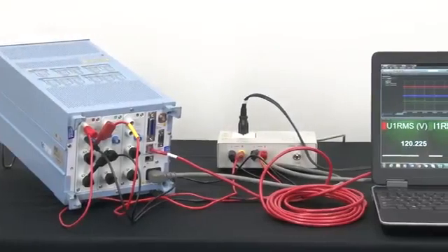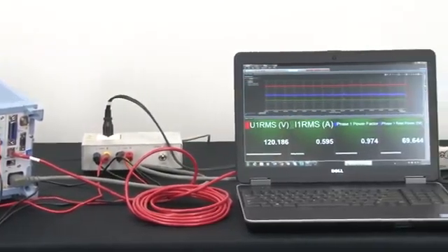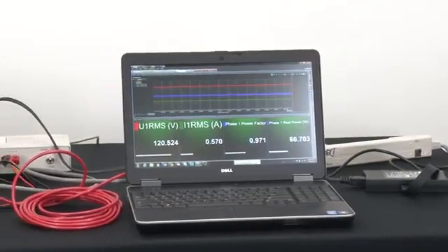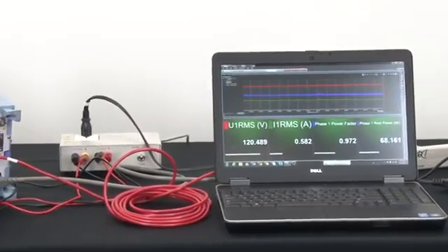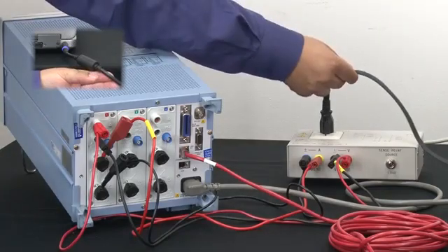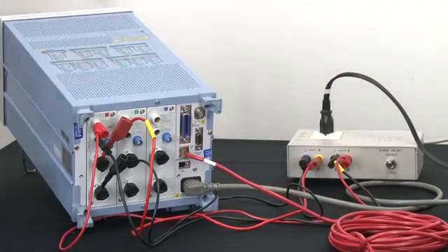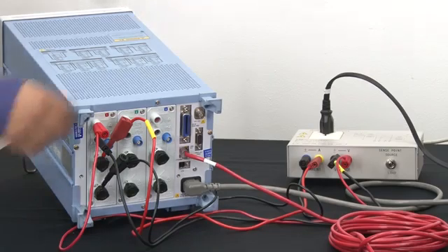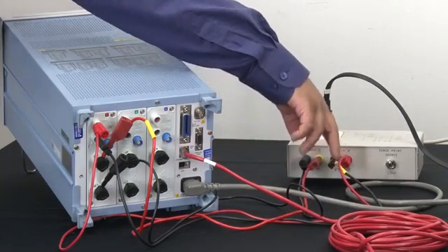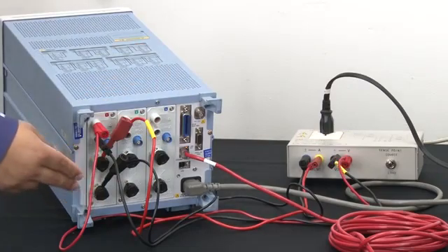Okay, so here I have a power strip, a custom load box, the load, which is my laptop, and an Ethernet cable, all pre-wired for a quick demonstration. To give you an overview, the main supply voltage, ideally 120 volts AC at 60 Hertz, is going into my load, the laptop, via the AC out. Power from the wall is going into the load box via the AC in. The load box has breakout leads that can connect to the power analyzer's inputs so that we can monitor the power being consumed by my load. As seen here, the voltage leads and the current leads.